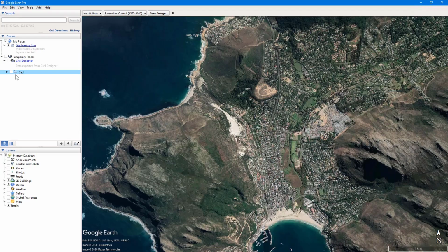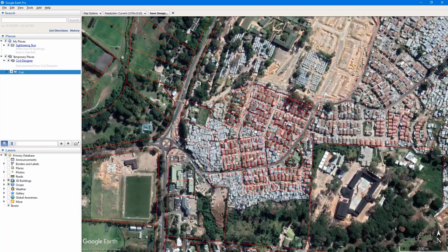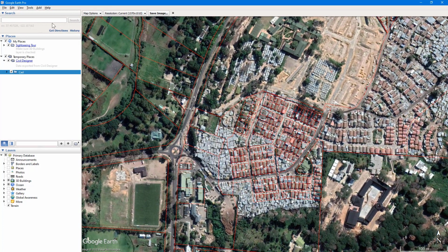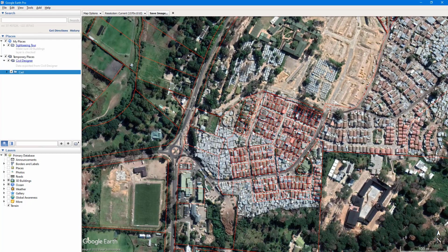And then you turn on the CAD layer again, and then you zoom into that position. Go and centralize it, and then go to View and reset the tilt and compass. This is purely for accuracy purposes. Now please note that you wouldn't want to base your final design levels on these extracted elevations. It would only be for preliminary project purposes.